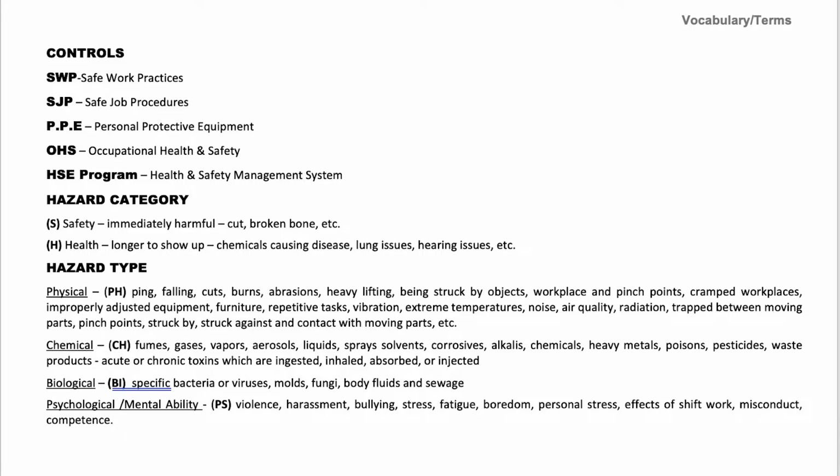The other thing that you want to ensure you have in place is proper PPE. This is personal protective equipment. And these could range from hard hats, safety glasses, face shields, face masks, gloves, coveralls, aprons, steel-toed boots, etc., depending again on the type of work that you are doing. Other things could also include safety equipment. This is fire extinguishers, first aid kits, flags, flares, pylons, reflectors, safety vests, warning triangles, those kinds of things.